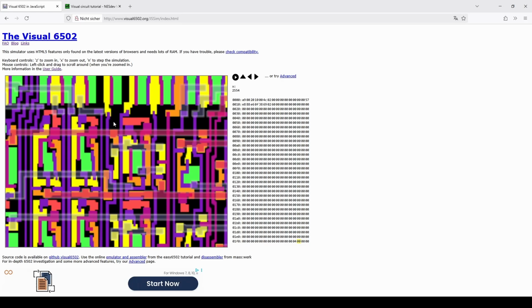Yeah, the NESDEV tutorial doesn't specify if that's supposed to be anything specific. I guess that's just air, because you've also got grey stuff, like maybe this stuff that's just metal. But anyways, that's not interesting. The point is, this could only go to ground via this silicon, and because this is currently off, so non-conducting, that means this has to stay on. It has to stay at 1. Okay, so far so good.